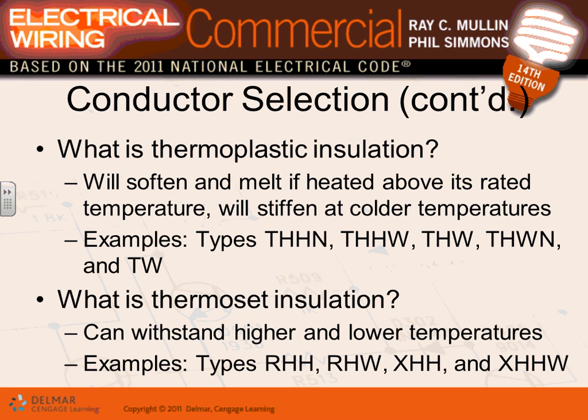So that's why we jump into the ones that are the best insulation for basically hot and cold weather, which is going to be RHH. I want to emphasize the high and low temperature. If you have an R in it, that's why they use these RHH and RHW. They use them for fire pumps and so forth. Most of us will be living right here, THHN/THW, done. That's where you're going to be living.